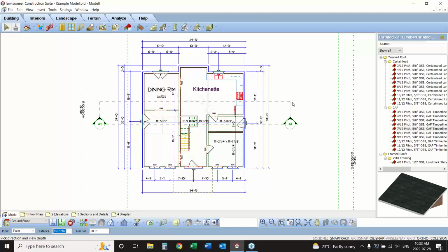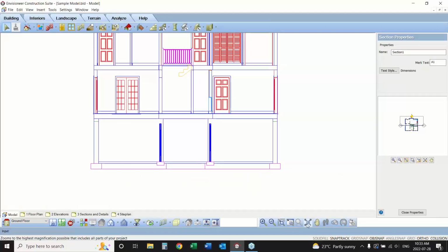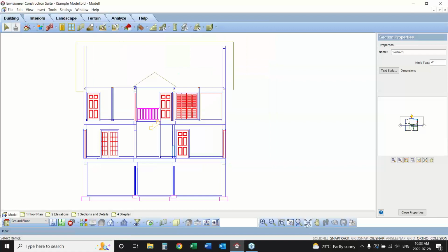As I'm pulling up, you can see that it's creating a rectangle. That's the visibility, how far back I can see. If I'm right here, I wouldn't be able to see the range or those cabinets or anything. But if I pick all the way back through my building, I'll be able to see all the way to the back. So go deep with your section lines and left click. And then it creates a section of the building, exactly where I cut it.